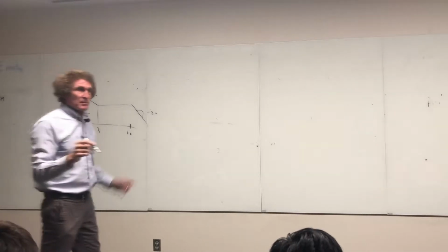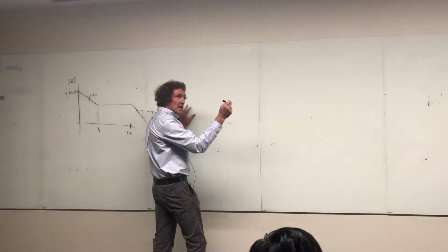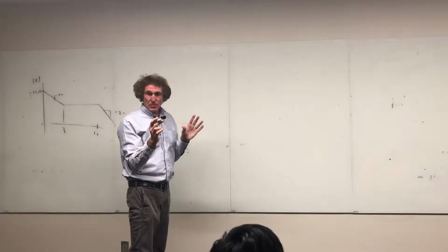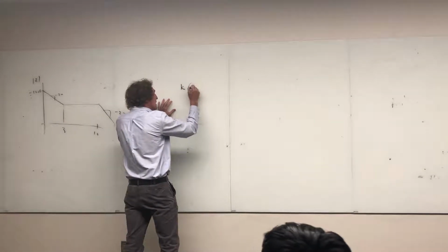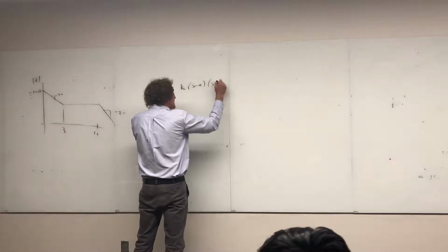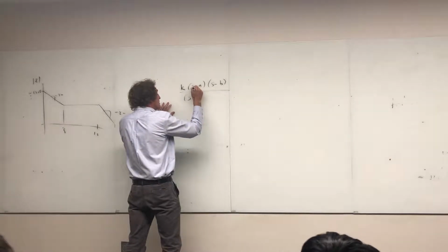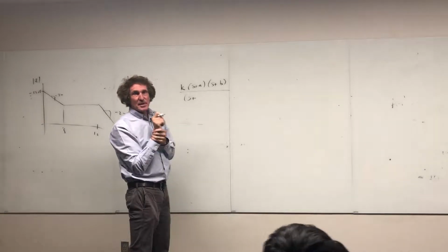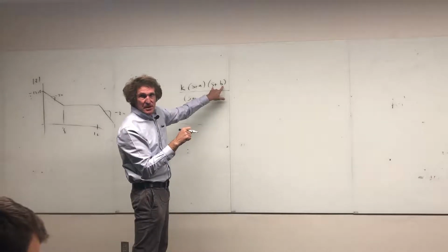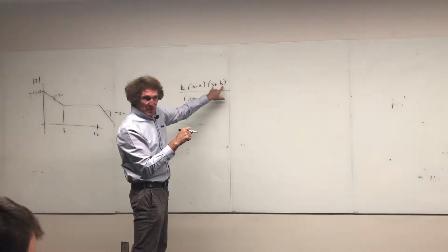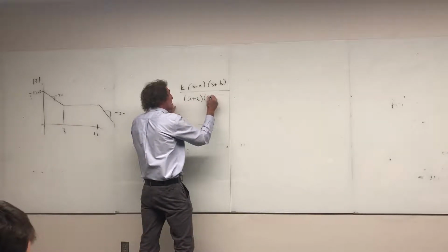In general, Bode plot, it comes down to one thing. First, if you have any function that's made up, and I'm just going to do first order poles on this one. We can do higher order poles. If you have something where you have K, and then you have S minus A, S minus B, and then you have S, either can be plus or minus. It doesn't really matter at this point because the zero happens where this is zero. Do you follow me in this class? When the quantity S plus B is 0. And then S plus C and S plus D.